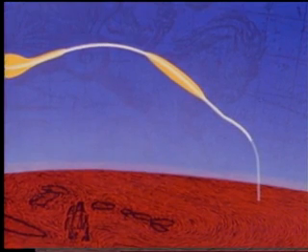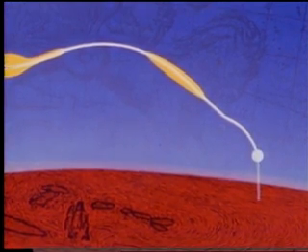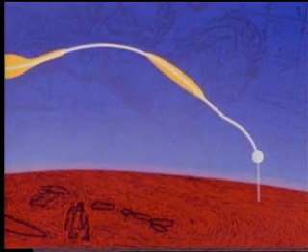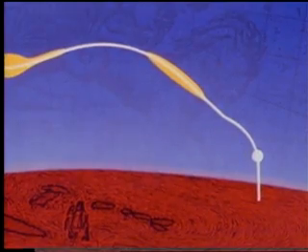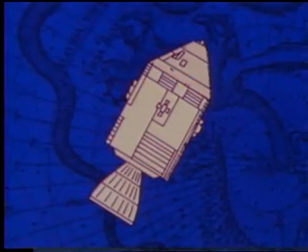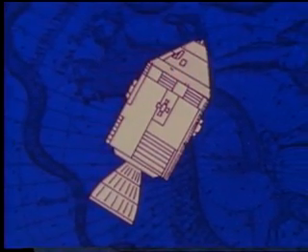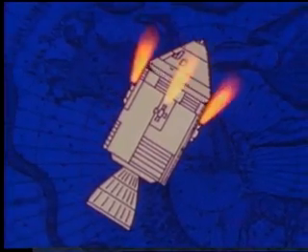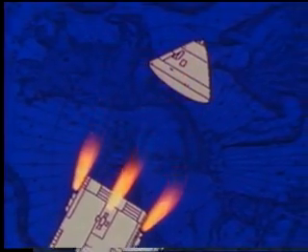The Apollo entry phase will terminate at about 23,500 feet altitude. At this altitude, the drogue chutes will come out, and the spacecraft will descend to splashdown by parachute. Reviewing now, we see that before entering the atmosphere, the service module containing all but the entry oxygen and power supplies will be jettisoned, and the command module positioned in its trim alignment.